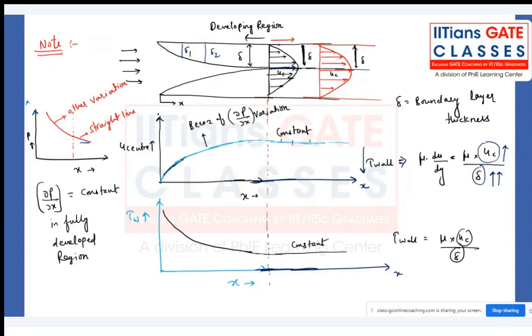For flow to happen, some driving force would be there, right? And what is the driving force for the u centerline velocity? ∂p/∂x keeps on decreasing at a rapid rate, but further on it is not decreasing, it is constant. The gap is there, means a difference is there, but that difference is constant for every instant as we march along the x direction. That's why the centerline velocity is not fluctuating; it will remain constant like this. Now, once it is done, let me know.